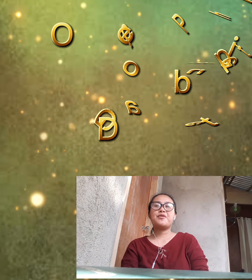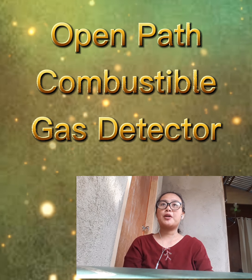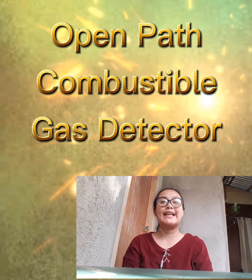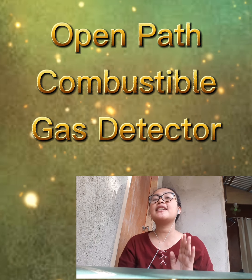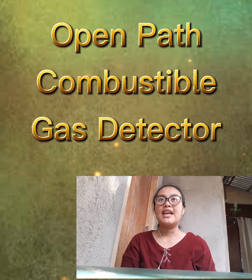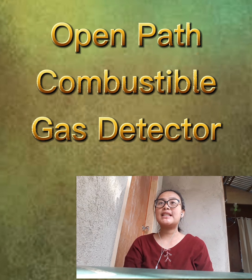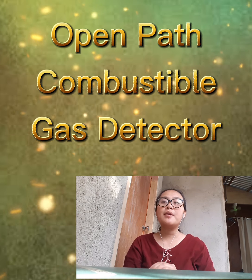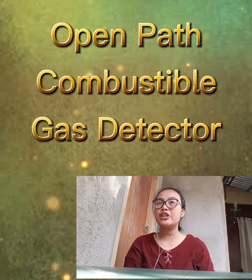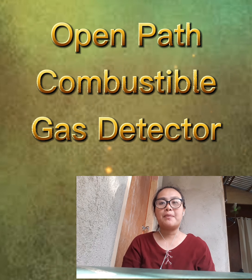The open path combustible gas detector shall operate on the principle of absorption of infrared radiation by gas anywhere along an open path, and it is also detected by photoelectric means, which produces electrical signals to provide alarms and indication of the concentration of gas along the path.